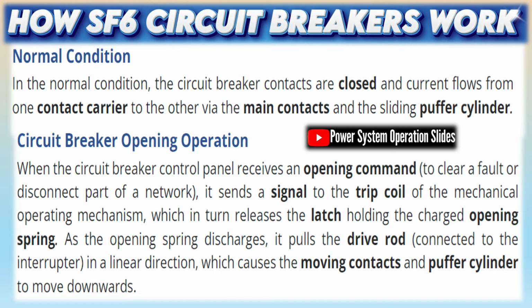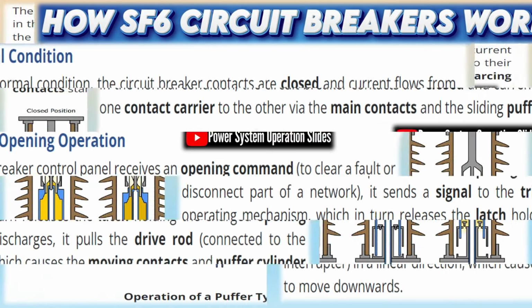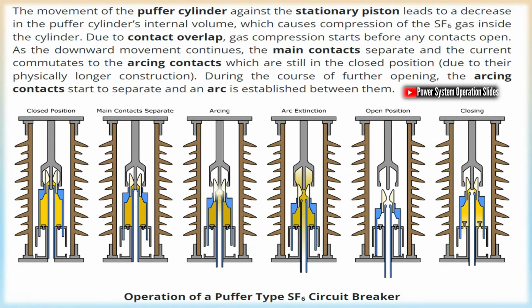Whilst closing, a circuit breaker can sometimes experience an event known as pre-strike. As the contacts move towards each other during closing, the contact gap's dielectric strength decreases. At some point, the voltage stress across the contact gap exceeds its dielectric strength, thus producing a pre-strike arc which bridges the contacts.